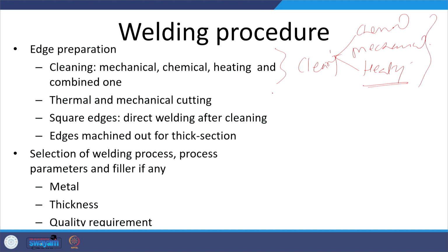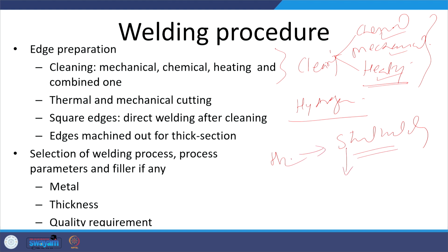So, cleaning can be done using chemical method, mechanical method or heating, but the thing is when we are using hydrogen based chemicals for cleaning purpose, then in case of steel welding, hydrogen tends to get into the steel, and when the steel with the hydrogen is subjected to welding, especially in hardenable steels, it causes cold cracking. So, those kinds of possibilities need to be avoided. If chemical cleaning has been done, then we need to take care of the hydrogen if it has been introduced.